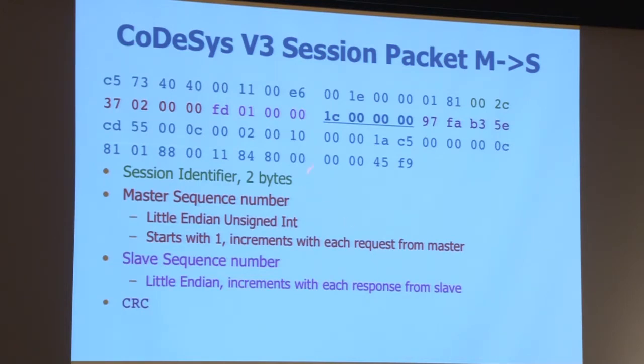And then I was just putting these slides together and noticed that this is actually a length field here. So this is a little endian length, and then this is the CRC of the packet. And then the rest of the packet here is the number of bytes calculated here. So that should be right, if I did my math right.